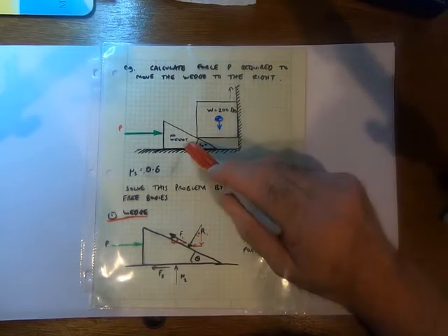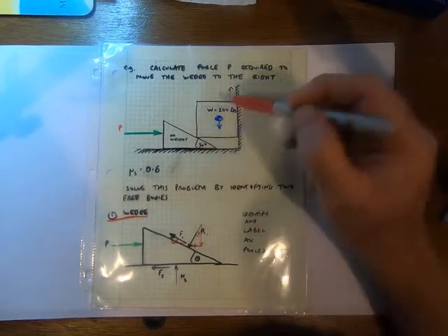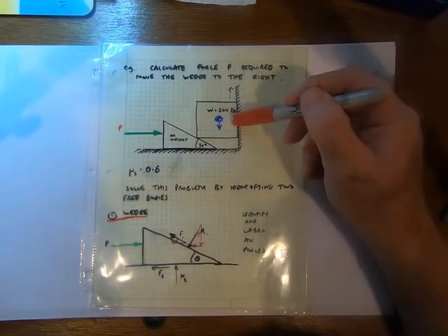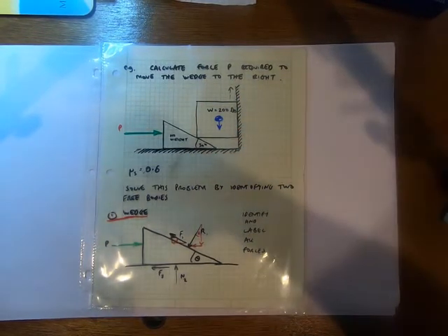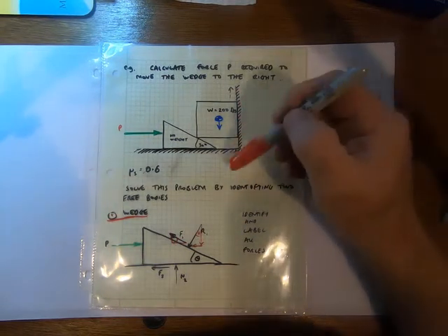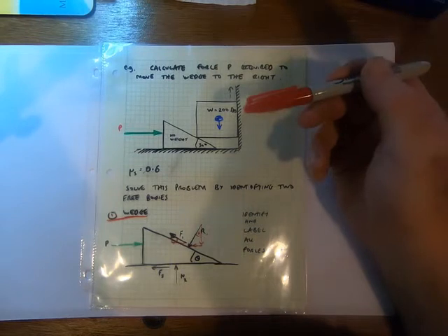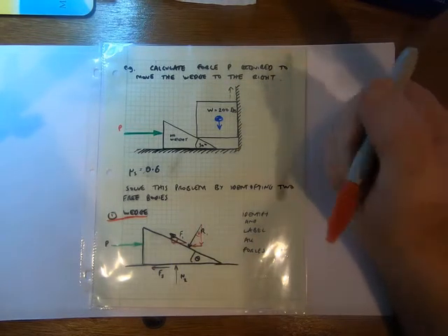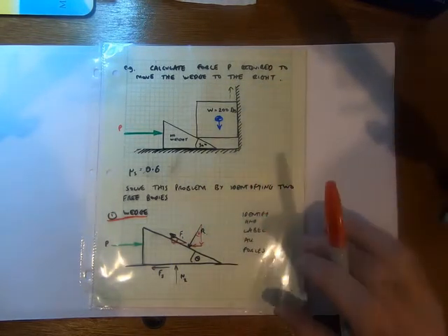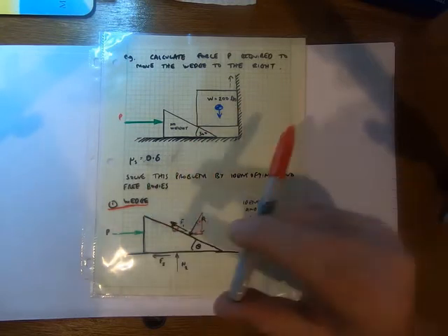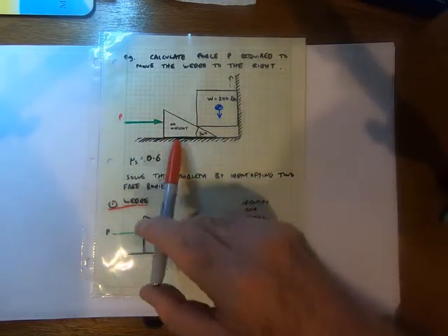So there's no weight on the wedge, this is just a shell, and then this is the actual cube with the weight in it. Notice there's no dimensions here, no dimensions are actually required. Friction is just F equals mu N, there's no mention of area in that, it's just to do with forces. So let's start, in no particular order, the way I've done here, with the wedge.